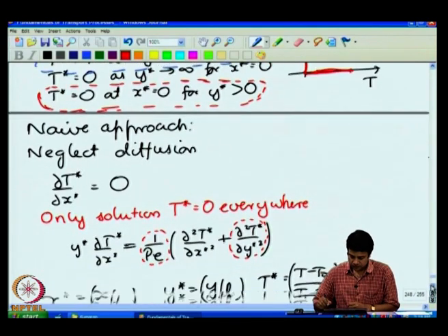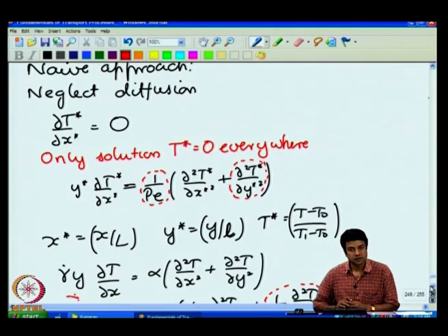And I had explained to you why, mathematically, there was this contradiction. When we neglected the diffusion terms, which contain the highest derivative, the second derivative with respect to the y coordinate, we lost the ability to satisfy both boundary conditions. In general, two boundary conditions can be satisfied, but when we neglect the highest derivative, we end up with an ordinary equation in the y coordinate, which does not contain any boundary conditions. And because of this, we are unable to satisfy boundary conditions.